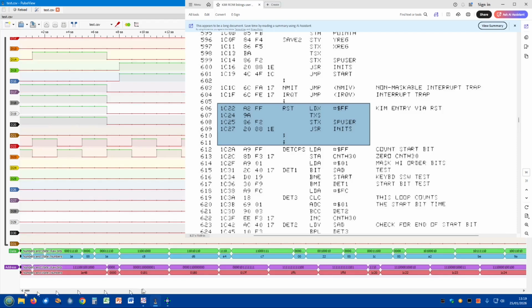Now, everything implies that the ROM is putting out the wrong code, but it could be the actual bus is stuck. What I think I'll do is I'll transfer this code onto a ROM chip, burn it in a ROM chip, and plug a card in with the actual code in. So make it so that it doesn't select the ROM chip that's on the main board, but it will select the ROM chip that's on the daughter board I plug in and run the code from there. And we'll see if we get any changes here.